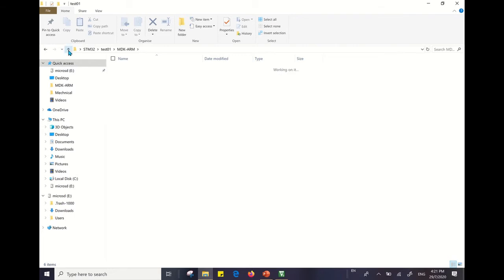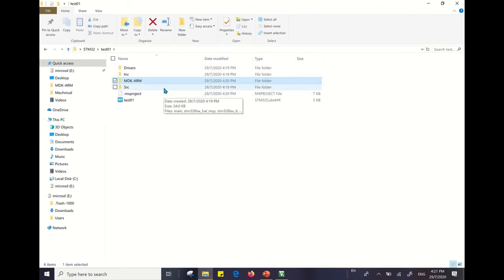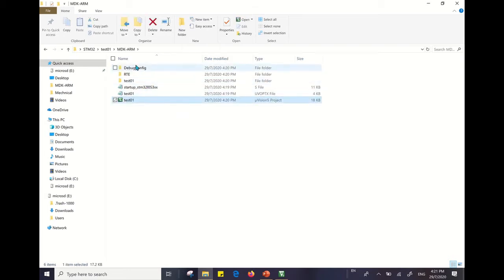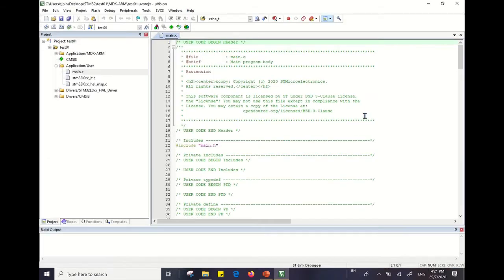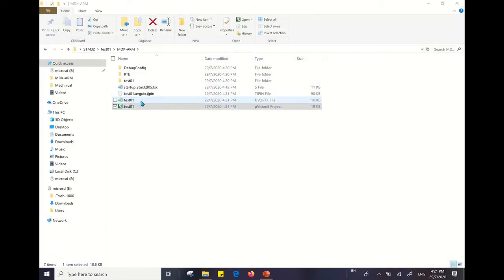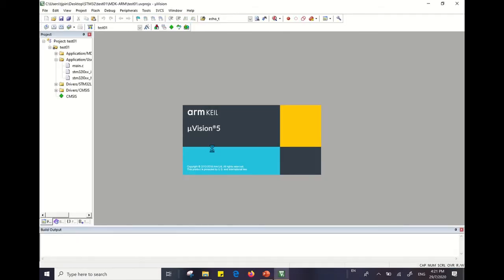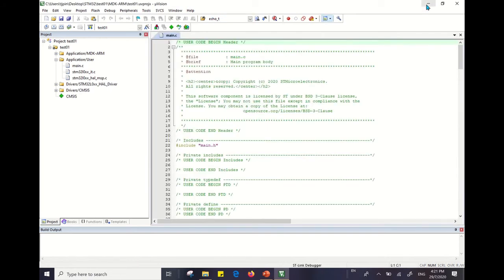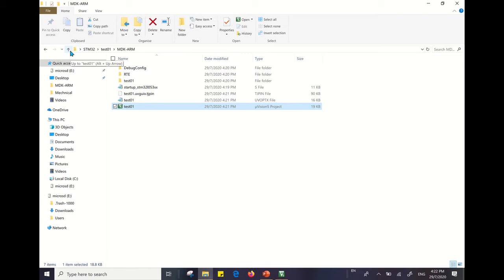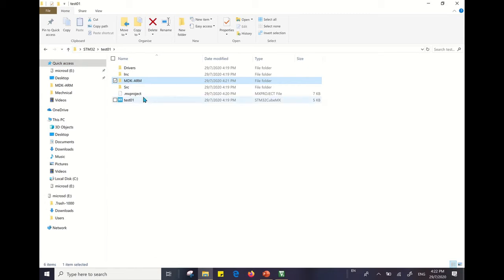Okay, sorry, the program for the Keil is placed under here, MicroVision project, which is under the MDK-ARM. So when we close the MicroVision Keil, you can open the project from here. So go to your project folder and MDK-ARM and double click on this, and you shall open the project. Okay, and if you have some changes to the initialization code, because let's say you want to change the clock frequency, you can go back to here, the MX. Just double click on this, you go into the CubeMX.